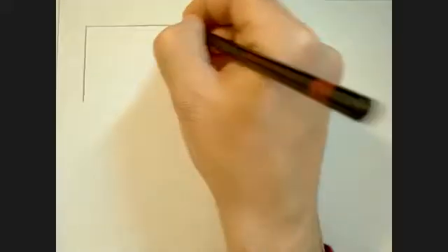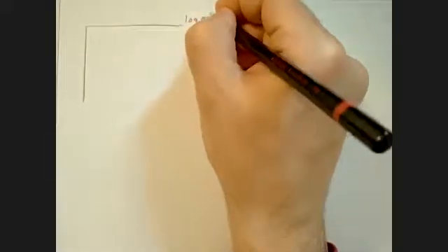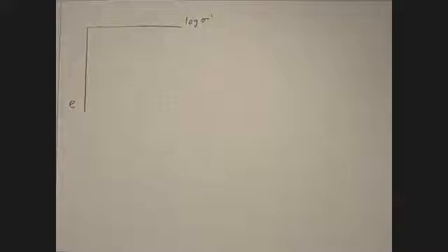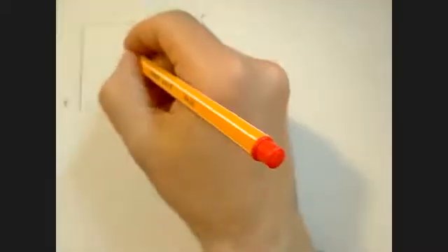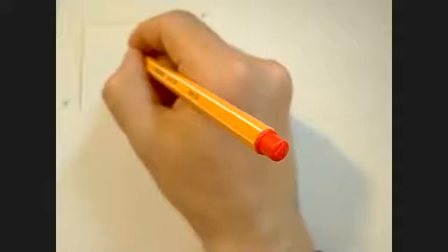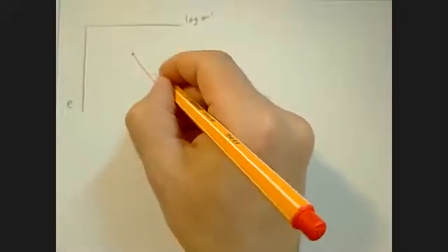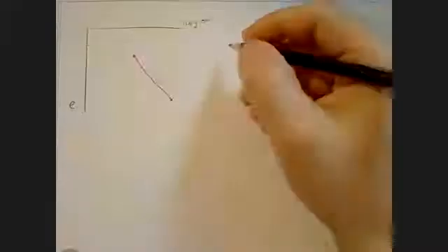So, okay, in order to help me think about this, let us again draw a generic graph here. So log stress versus void ratio. And if you are doing a normally consolidated soil, then basically this will be it. From here, from this point, I move to this point with a slope of Cc. So how much is my strain then?